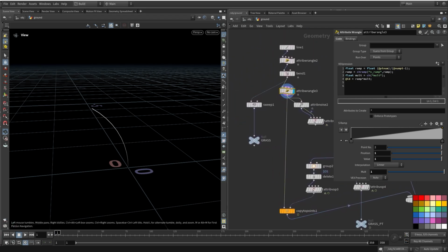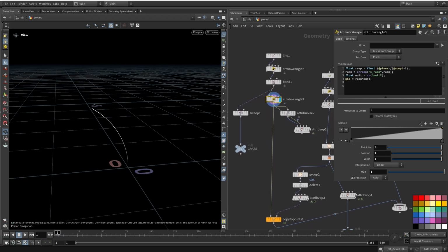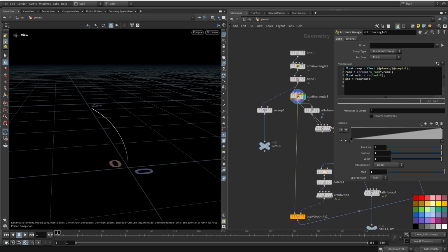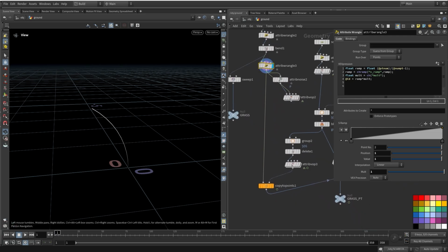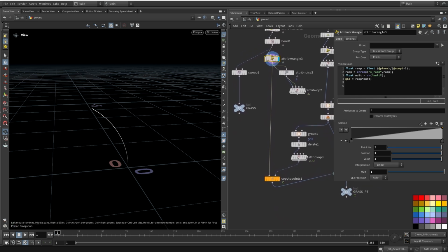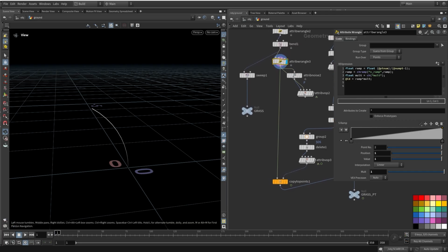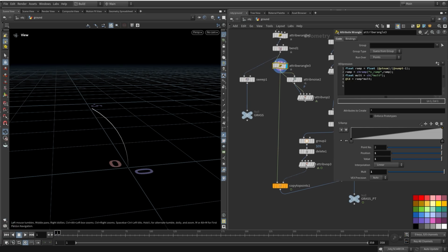First of all, you can simulate the grass as you simulated the claws, but I thought maybe I could try another way. Another way is to animate a single grass blade and then use for-each cycling and time shifting for each grass blade, which is very expensive for your computer, maybe for mine exactly.